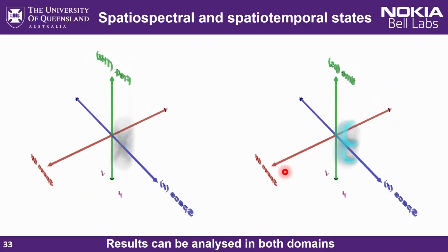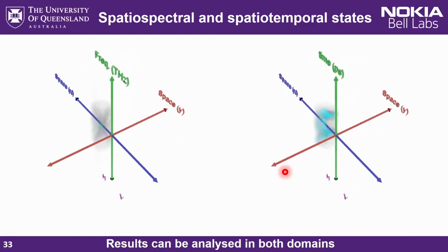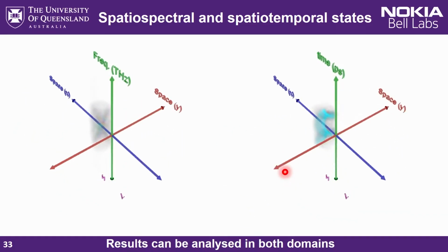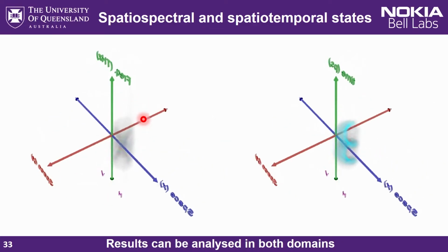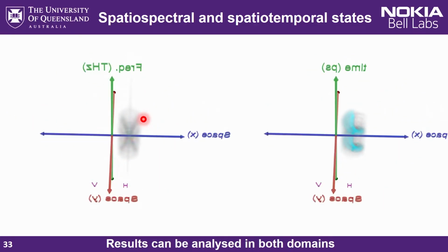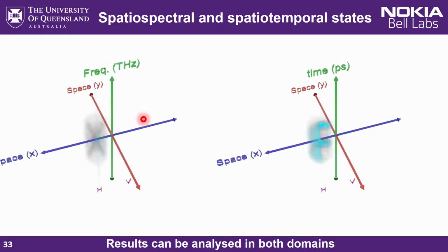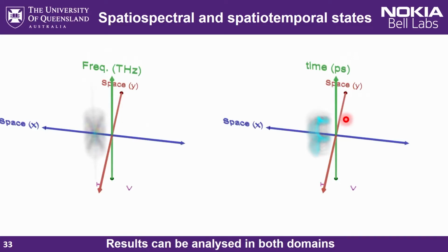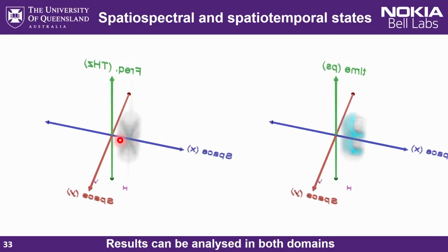Now we can generate arbitrary vector fields in the spectral domain on the output facet of the fiber, within the limits of the optical bandwidth and frequency resolution. The target is a set of 90 modal coefficients reconstructing a 2D spatial pattern at a given wavelength. For a target in the temporal domain, we just need to calculate the Fourier transform to get the target in the spectral domain.